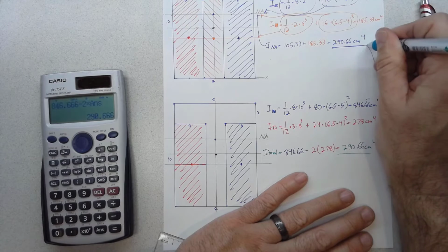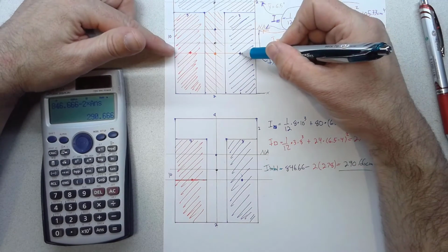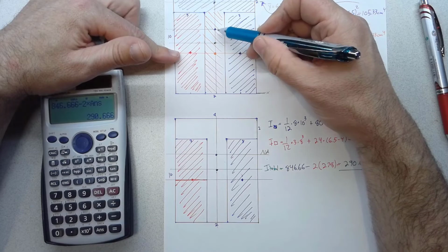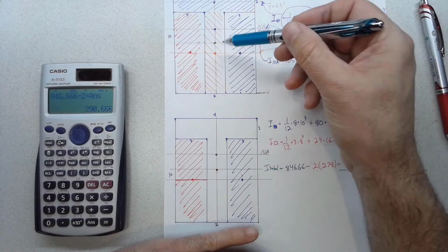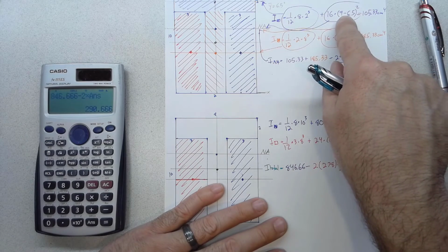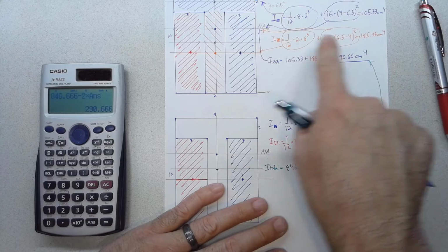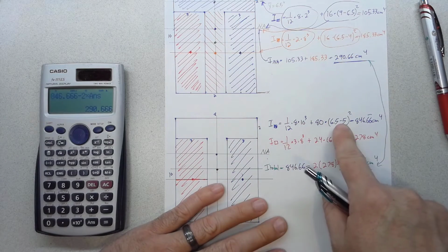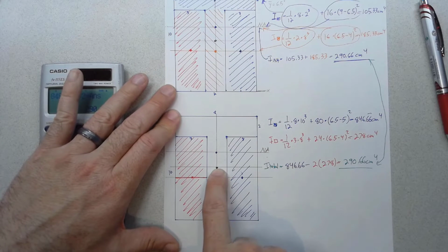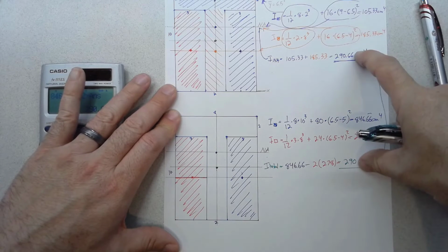Okay, so again, you can see same answer, just came to it a different way. Key idea here: now that our component pieces have a centroid located at a different distance from X than the centroid of the composite piece, the final shape, we have to use the parallel axis theorem for every term of I. You can see that every I that we used, we get I about its centroid axis, and then we shift that I to a new axis. So this part right here shifts this I from about this axis down to this axis. This part here shifts this from this axis up to this one. Same thing here. This part shifts this I from the total, the original neutral axis, up to the neutral axis of the component. This one shifts this I up to here, and we end up with the same answer.